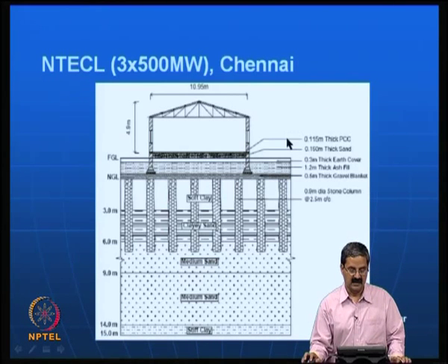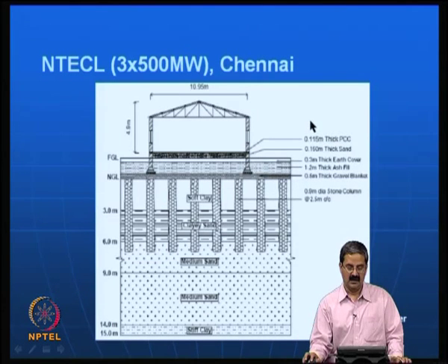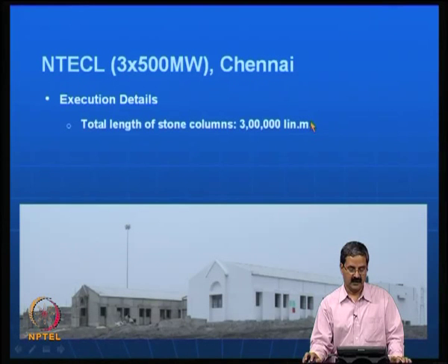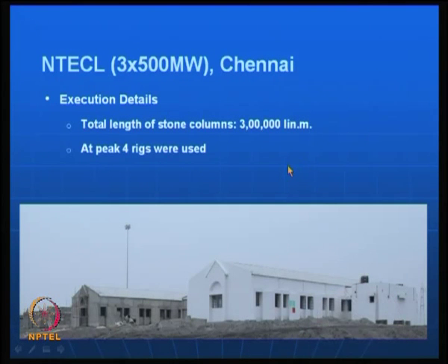You can see that soft soil is here, clay sand is here, then medium sand. So, you have a stone column in this form, which is very useful. There are so many columns, about 3 lakh, or 300,000 linear meters of stone columns were used, and the installation period took more time, 20 months here.